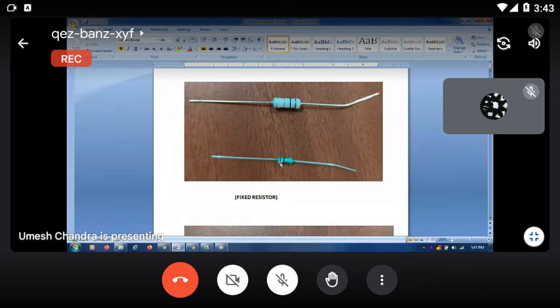In the other case, for a second, small resistor, you calculate its resistance value by using the color code and multimeter, the same procedure. But here are two resistors, one bigger and another smaller, so the size is different. Why is the size different? It depends upon their power. What is the unit of power? It is the watt. The bigger resistor is a 1 watt resistor, and the smaller one is a quarter watt resistor. Maybe 5 watt, maybe 10 watt, maybe 2 watt, maybe half watt. This is due to their power or wattage.